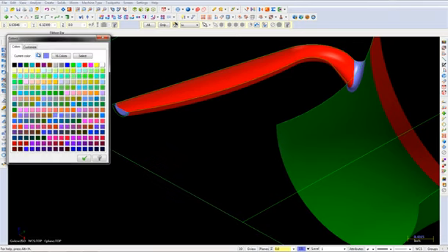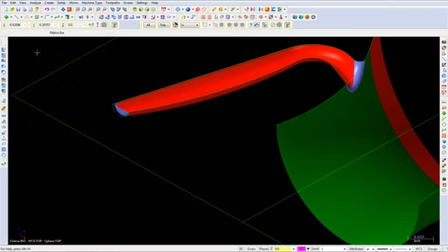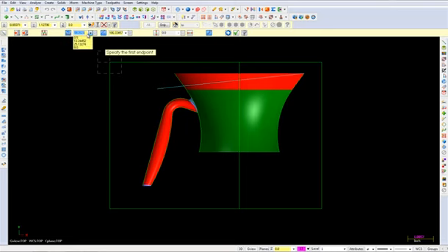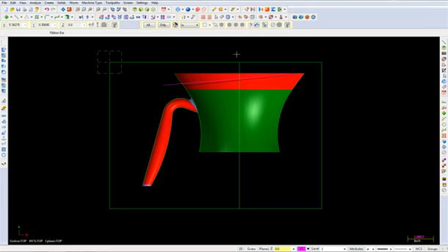Change the main color to magenta number 13. Change the graphics view to top. Then choose the command Create Line Endpoint. Choose the first endpoint to be here and then a point over here. Change the length to 6 and the angle to 185 degrees. Select the OK button to exit the command.